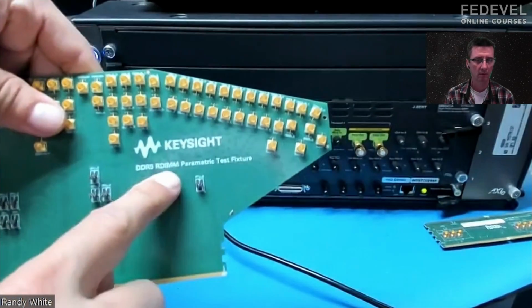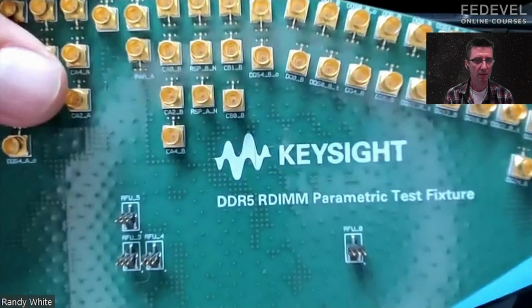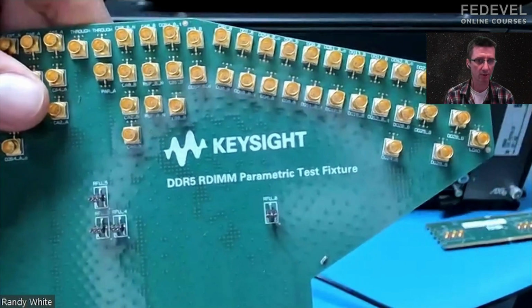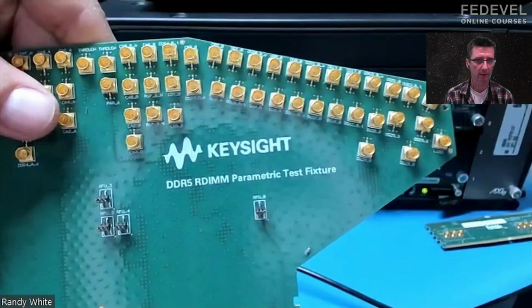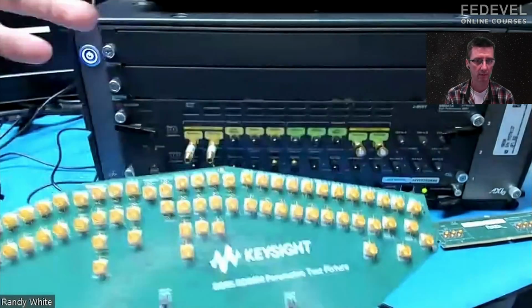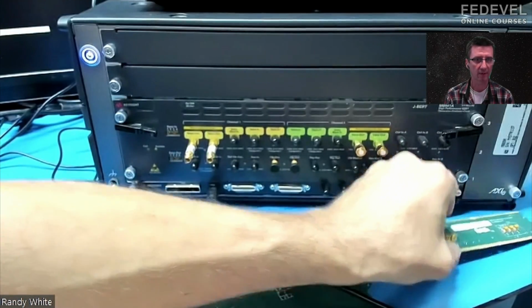This is an RDIMM parametric test fixture. Okay, so this is not for measuring the memory chips. This is kind of, you measure the controller. I measure the controller, the memory controller, or possibly the system, PCB layout and the connector and everything together.